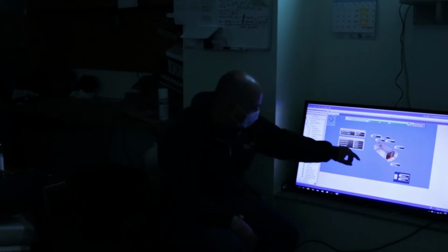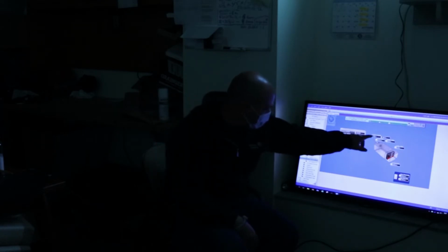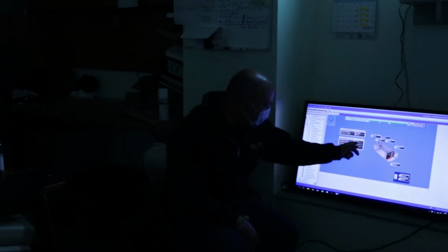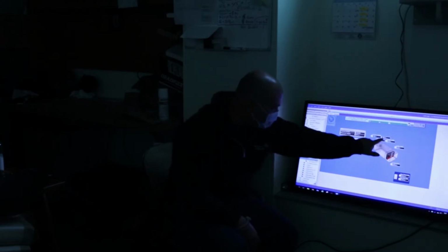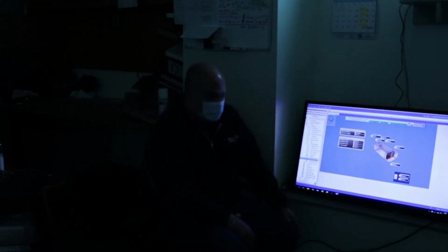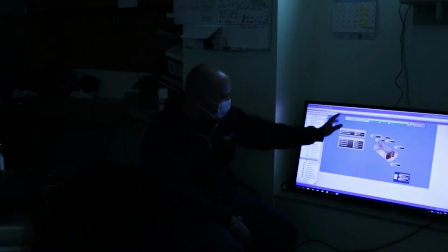And if we're further away from the set point, we'll be at 285. So you can see what the actual flow is and what we're looking for. Right now, we're looking for minimum, right? We're right at 100. We're in heating, so it's pretty much the same as minimum. So we're looking for 146, and we're doing 158. So we're looking pretty good on this box. Hopefully we'll see the room temperature rise, get to that 72, but it's nice and slow and controlling good.